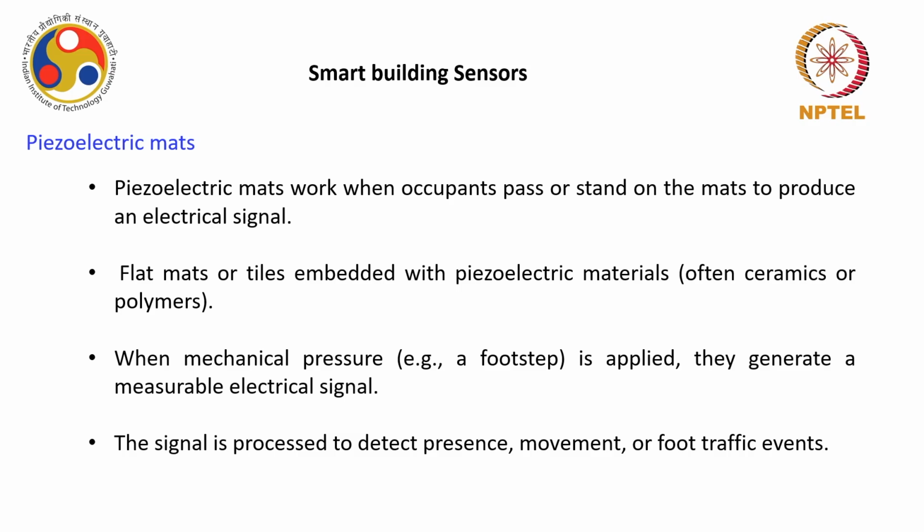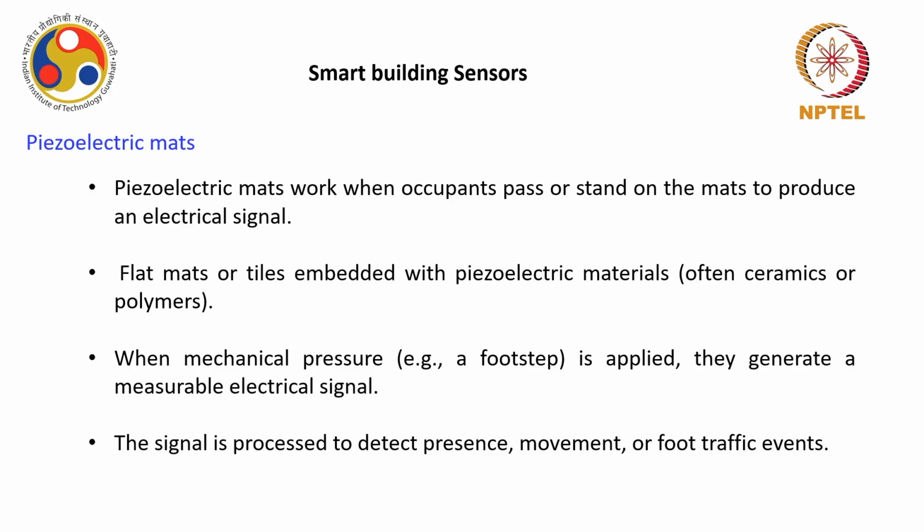Okay, piezoelectric mats work when an occupant passes or stands on the mat to produce an electrical signal. Of course, these mats are not simple door mats. They are basically flat mats or tiles which are embedded with piezoelectric materials. This can be ceramic or polymer based. We have seen that in detail in our previous module, like PVDF and quartz kind of materials. Okay, so when mechanical pressure is applied, for example, by a person's footstep when he is walking,